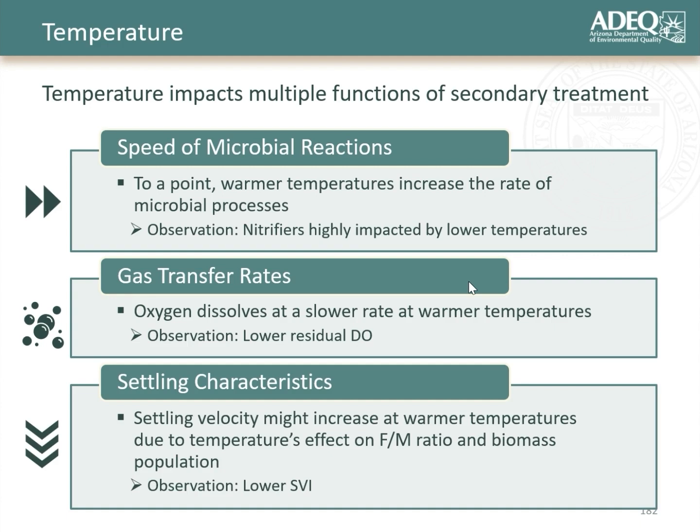And then lastly, we talked about this earlier, settling characteristics. As the temperature warms up, the water becomes less dense, and as it cools, it becomes more dense. As it gets cooler, that higher density can then limit how quickly things will settle, depending upon the density of your floc.